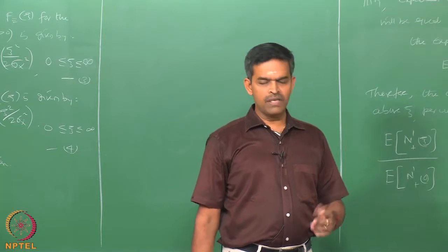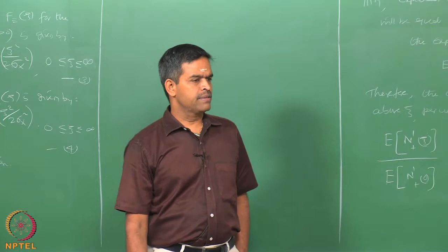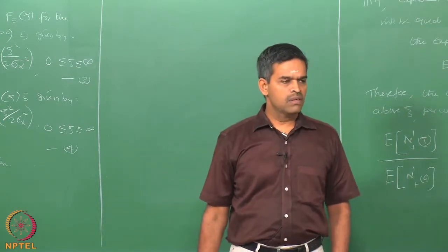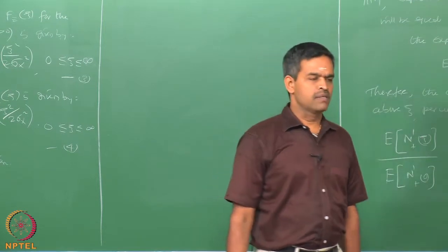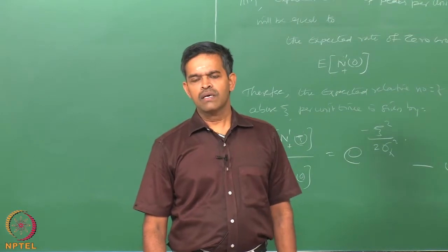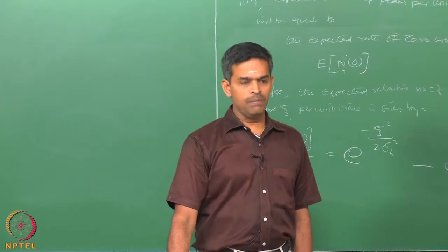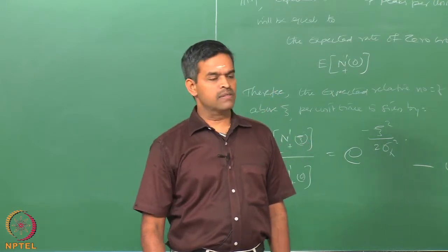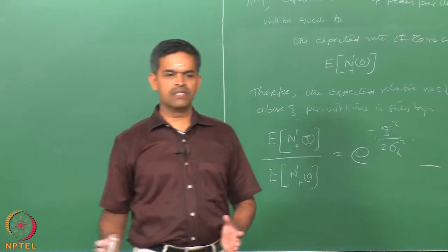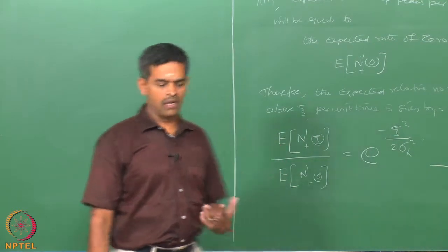So, the concept we discussed so far as the barrier crossing can be usefully applied directly in fatigue reliability analysis, which we will discuss further. I will also take up a case study where we have estimated the tubular joints capacity, which can be one of the important inputs for reliability analysis of offshore structural joints. So, let us now expand our discussions further with the background of stochastic process on to fatigue reliability.